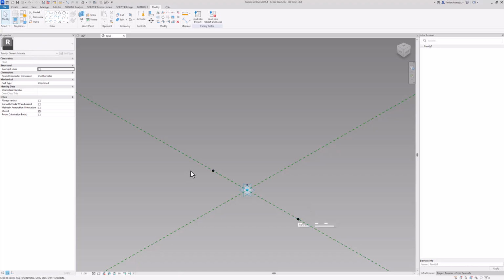So we have the width of our element defined. Now we want to create our rectangular cross-section. There are again multiple ways to do this. I will show you the approach in which I simply assign a length and a height to the whole cross-section.